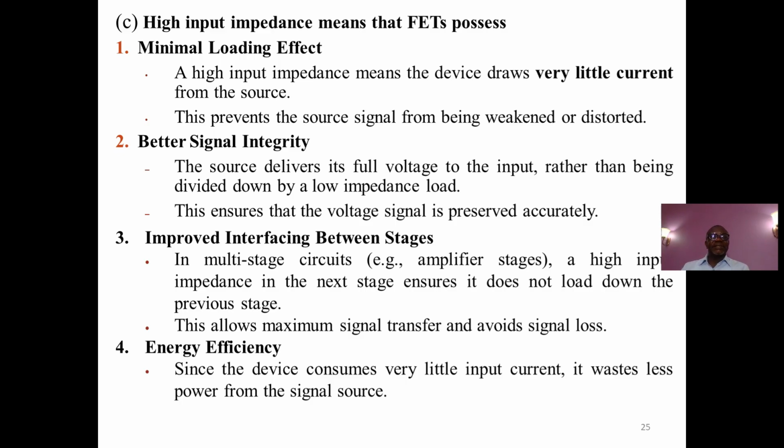In any system with high input impedance, we have very good signal integrity. That is, the source delivers its full voltage to the input rather than being bogged down by a low impedance load. This ensures that the voltage signal is preserved accurately.